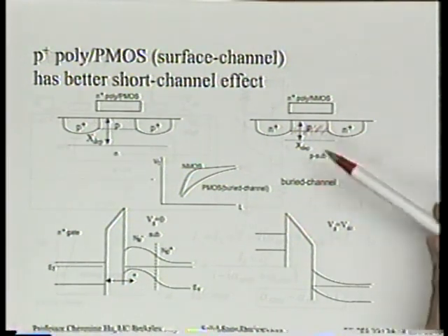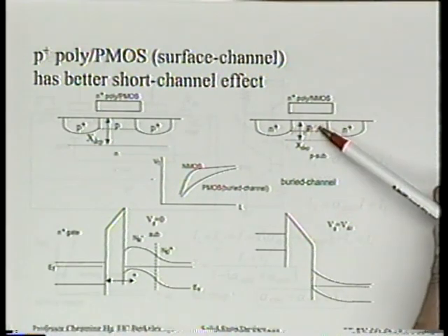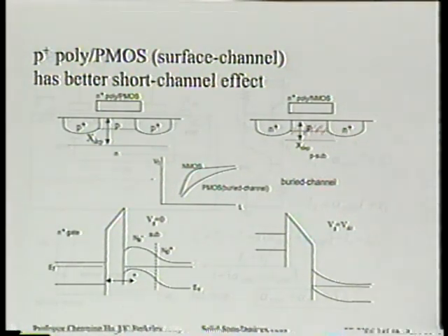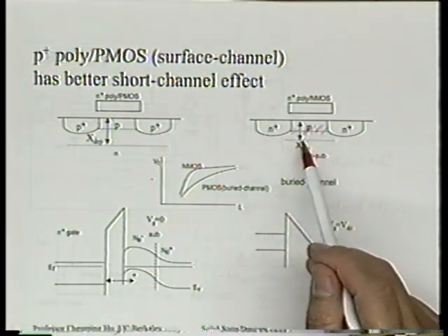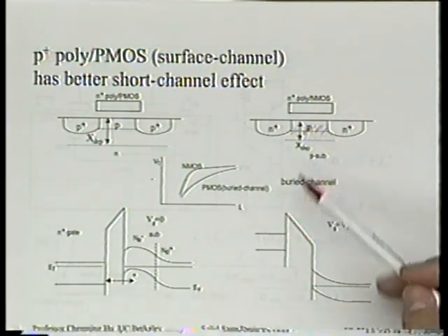We dope the well so heavily that even without that surface boron implant, we already got the VT we want, in fact more than what we want. So we actually go to the retrograde doping profile with the doping density lower near the surface. So in this case, the depletion region width is smaller. Is that right? And we already argued why we want to go to ideal retrograde doping that actually allows us to get 1/2 X depletion for the same VT compared to uniform doping.